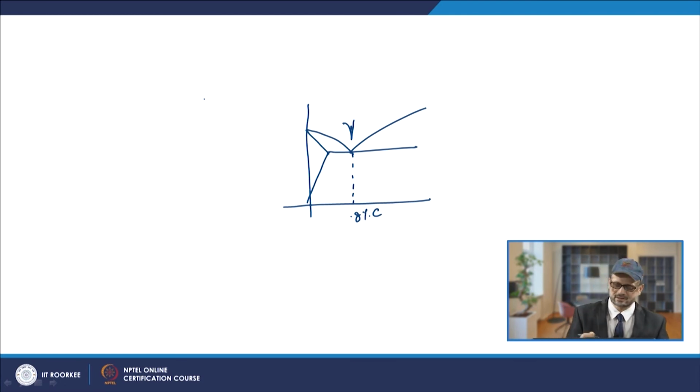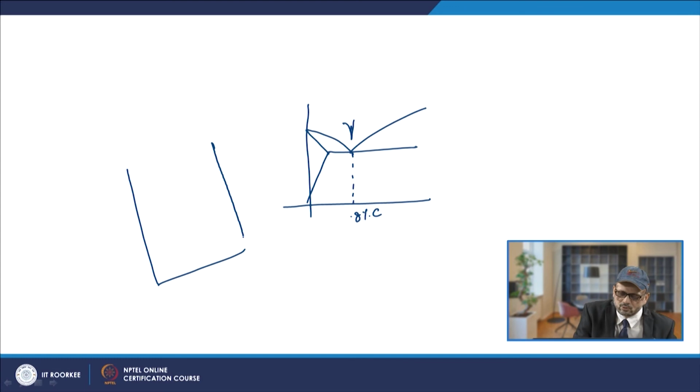So, if you look at the hardness of martensite with respect to carbon, what you see is that if it is more than 0.4% carbon, then there is a steep increase. The graph suggests this. So, if you look at the graph of hardness versus the carbon percentage, this is hardness Vickers, and this is the percentage carbon, say 0.2, 0.4, 0.6 and 0.8.